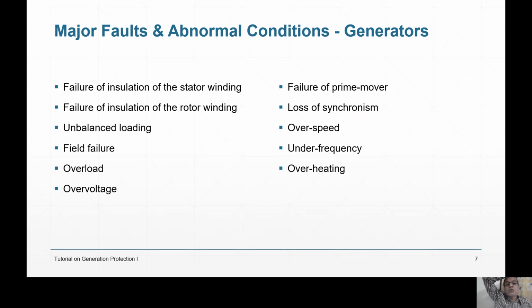How to do load shedding, in what steps you should do it. If you have to cut 10 megawatts, then you should cut first 2, then 2, then 2, or 4, 4 and 2, or 5 and 5, or 10 at a time. I mean, it is a complicated phenomenon. Load shedding, synchronism, all these are subjects by themselves. Everything we will not be able to see, right?